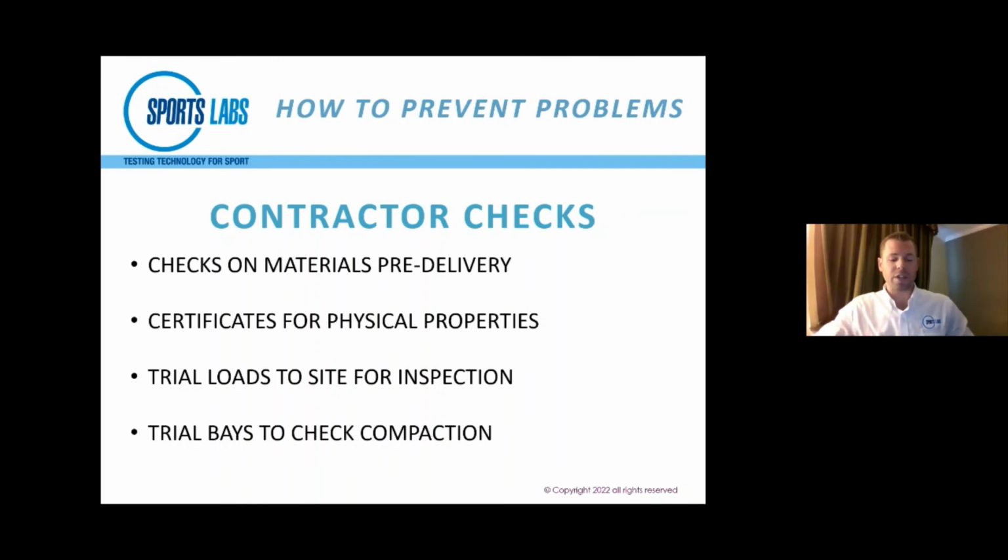And then for drainage, that could be something as simple as running a hose along the base and just running the water, seeing where the water goes. Again, it's a pretty quick and dirty way of verifying: is this water draining vertically? Is it going where it's supposed to go? How fast is it moving in the direction that it's moving in? And then, of course, we can come in and verify that and produce an actual third party report that says, all right, this field is in fact built to spec and does what it's supposed to do.